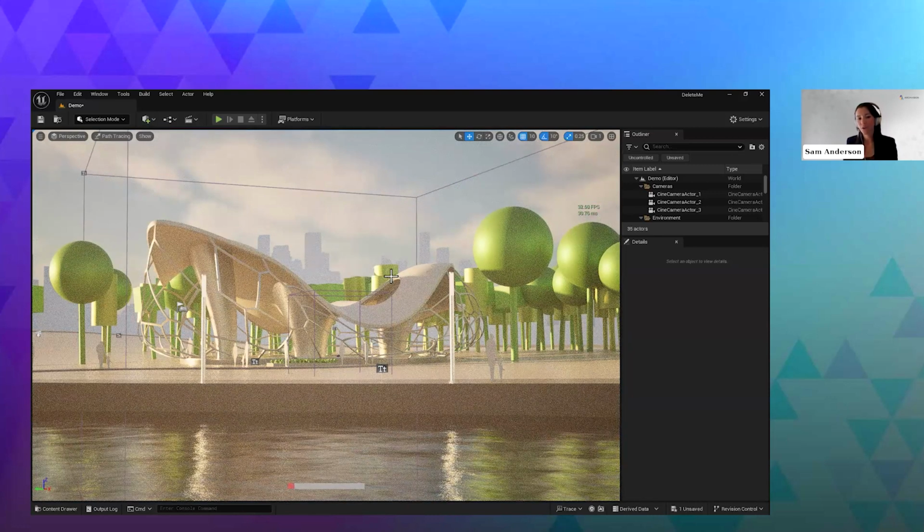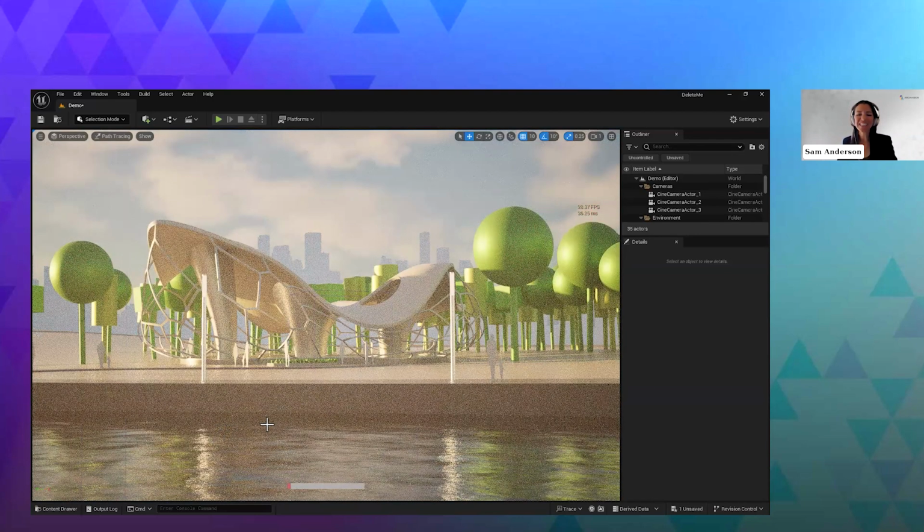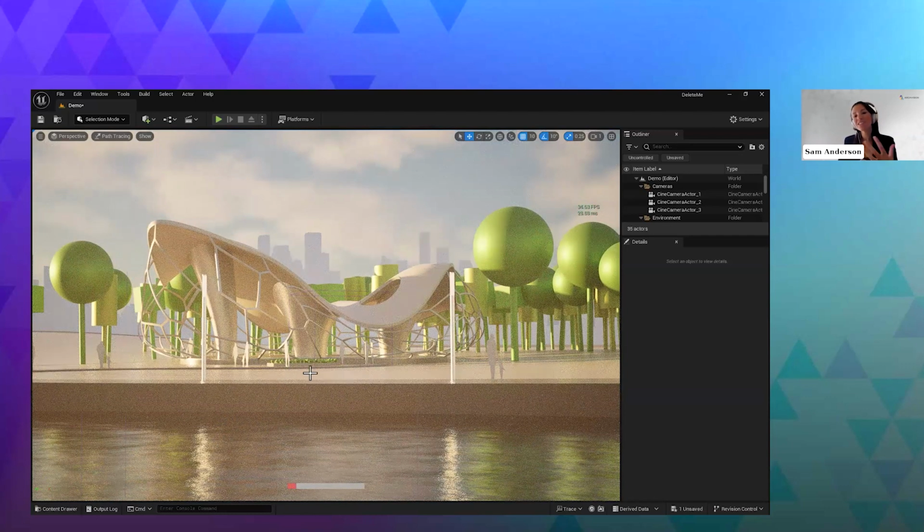This is your progressively rendered screen here, and what it's doing is calculating all of the different lights inside of the project and making sure it's giving you improved reflections, refractions, and a little higher quality, more accurate rendering. Now you'll see that the water's a little blurry here. There I have my grid on, so you can hit G to toggle that on, and what that's doing is turning game mode off and on. But essentially this could be used to produce really high-end renderings.